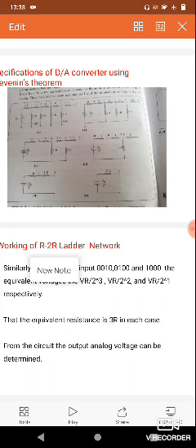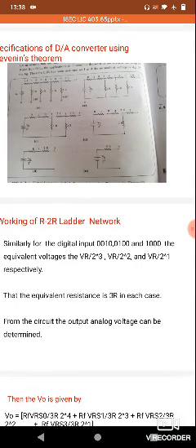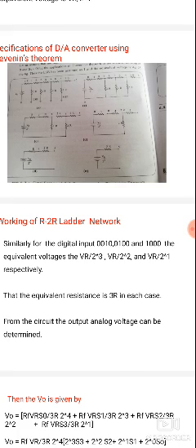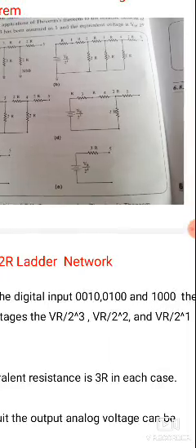Thevenin's voltage is called V Thevenin, and Thevenin's resistance is called R Thevenin. So, Thevenin's resistance is the resistance between the two open terminals with all sources replaced by their internal resistance. By using this we can calculate the circuit.